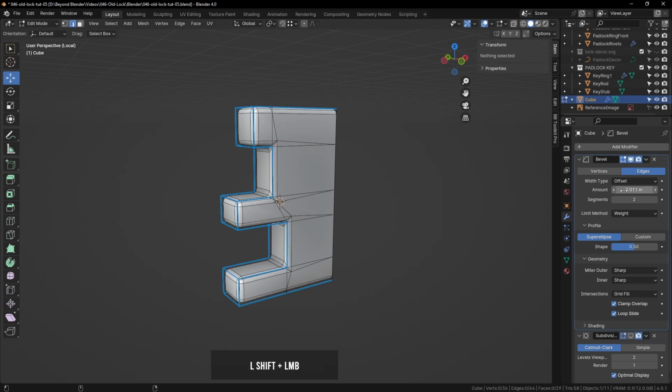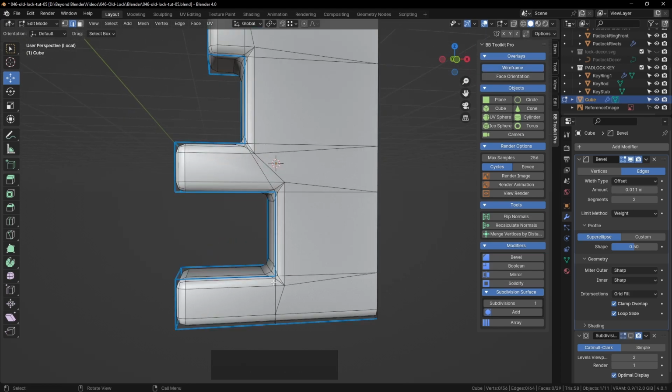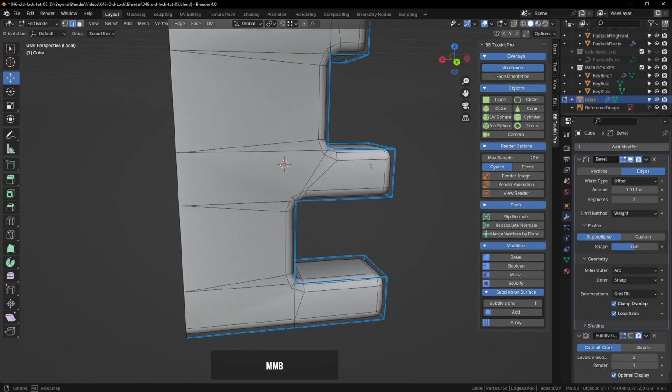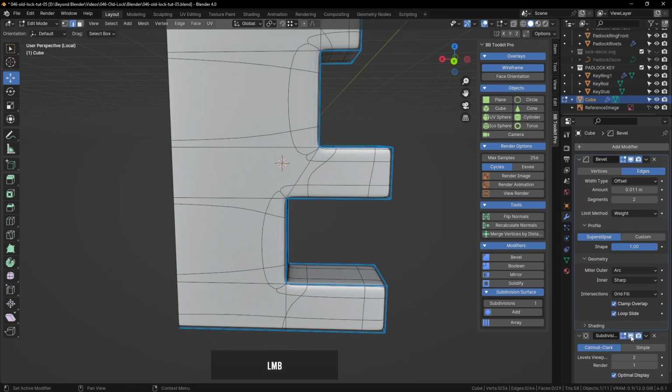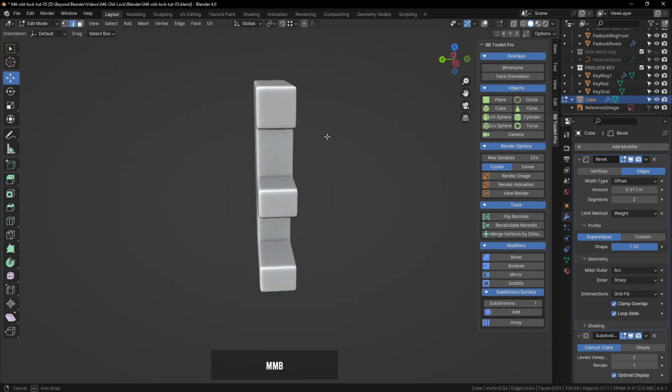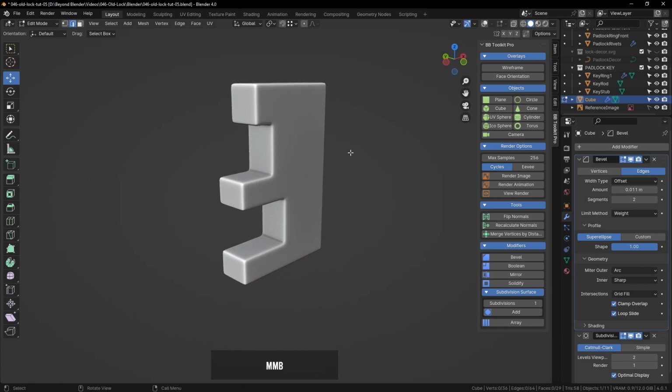And this is good, but notice the corners, the recesses, they kind of pinch into a point, which is horrible. You really don't want that there. You can change that by changing the miter to arc. That's much, much nicer. I don't know why that isn't a default, to be honest, because patch, or sharp, I should say, never really works perfectly in all scenarios. Arc does a much cleaner job. That's looking really nice and clean.